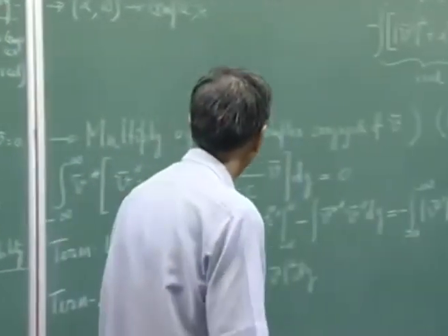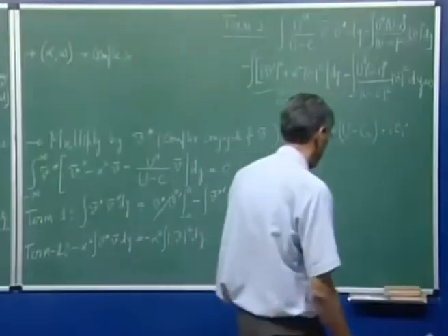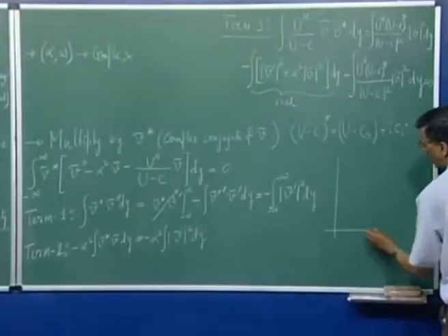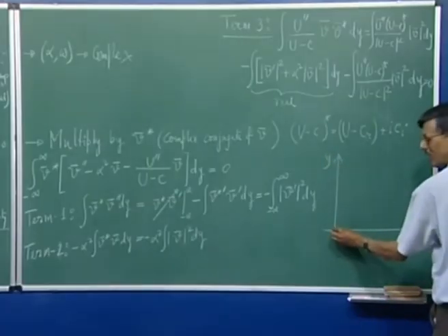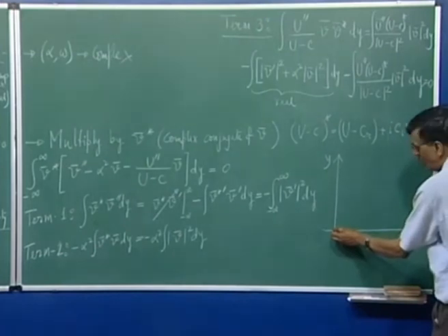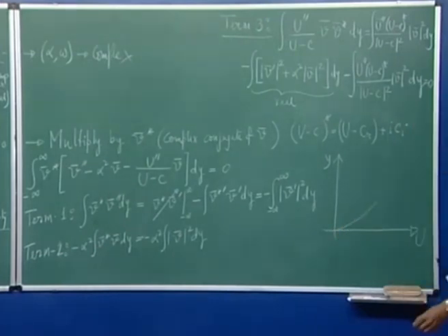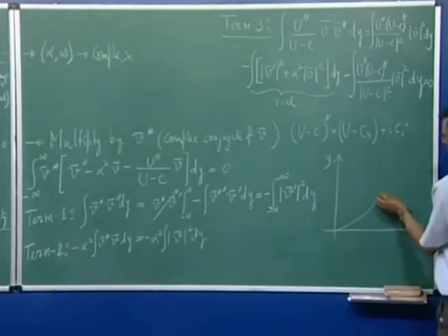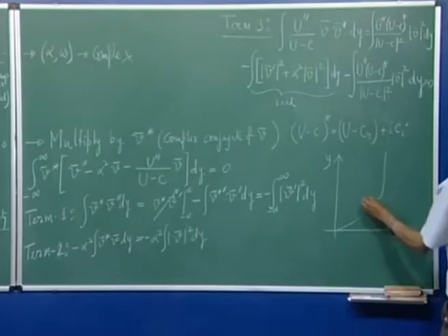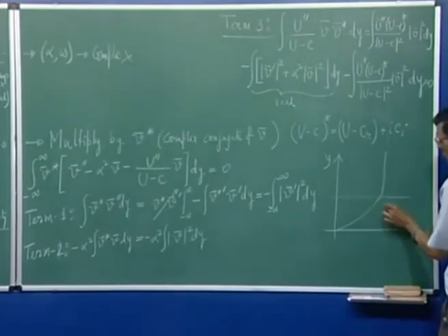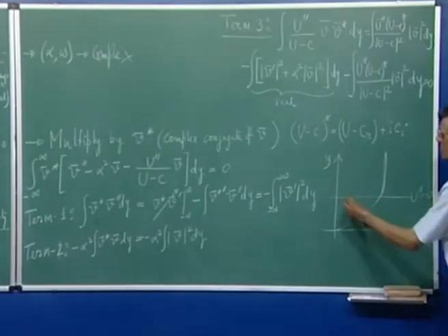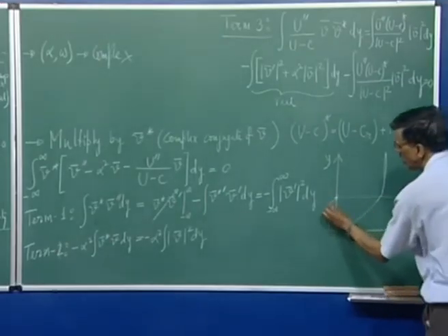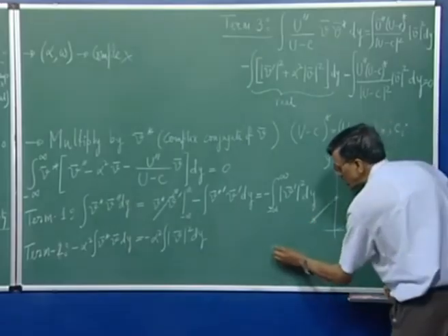So if I am talking about a velocity profile, which we sketched before, I would have a velocity profile where it will have, let us say, a positive value, then it will have a negative value, I mean 0 value somewhere. Okay, so there would be a place where I will have u double prime equal to 0. So this point is called the inflection point.